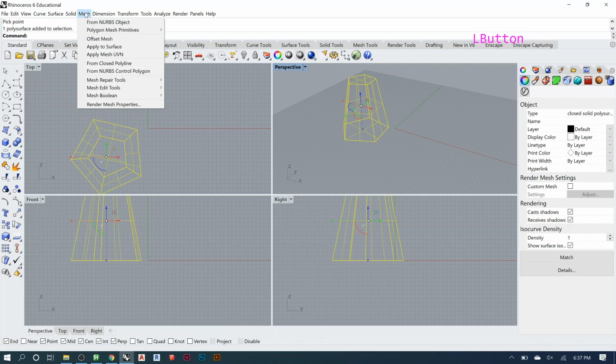So when we start looking at how Rhino is set up, you'll see that it has way more variety in the type of geometry you can draw than you could in SketchUp. In SketchUp, everything is polygon based and is based on those little triangles. Rhino doesn't need those triangles. It can work a lot differently and a lot more fluid. It can also create that type of geometry with all the polygons, and that's considered a mesh. So if you find mesh geometry, think of that as something that's been modeled the way it was in SketchUp, where it's all faceted.